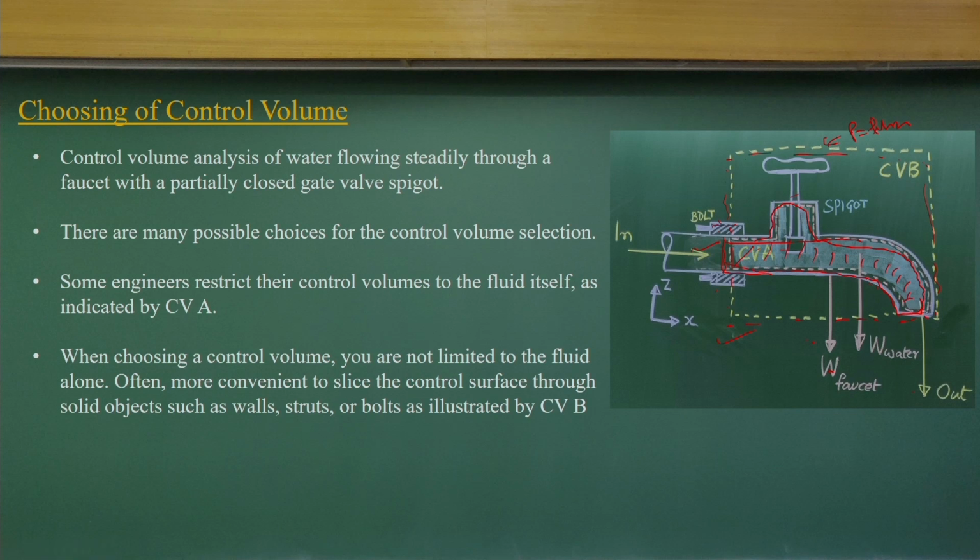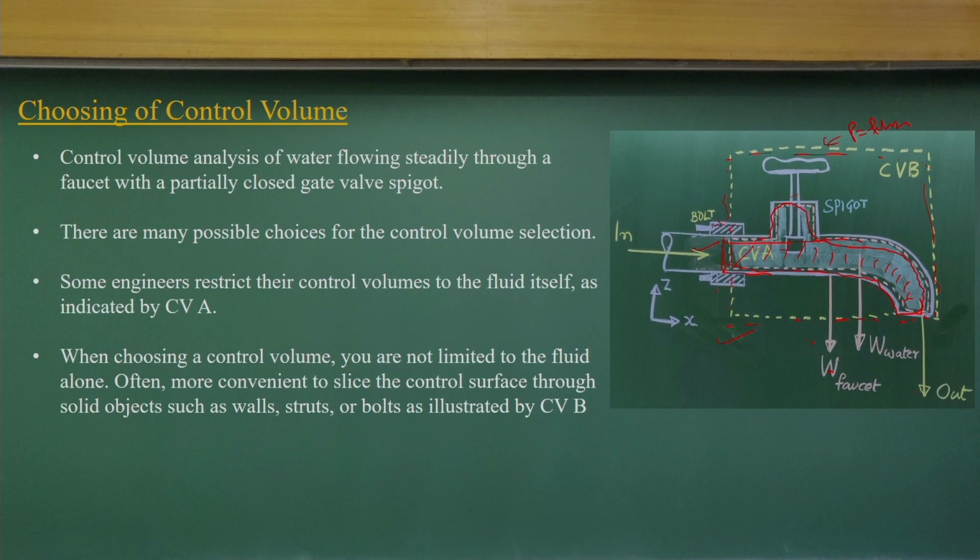That is the point: it is an engineering skill, or art, to be developed by the students, how to use the control volume concept and how to define the control volume for a flow system so that you can easily solve it. Another thing we do is that when you define the control volume, the control surface should have a normal and the velocity should be aligned to that.